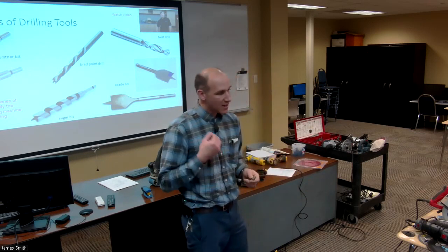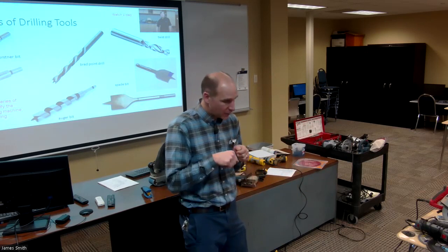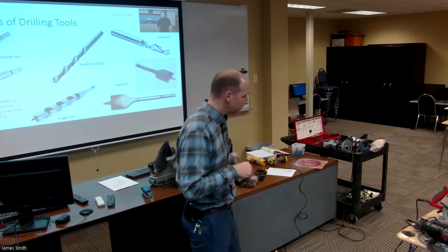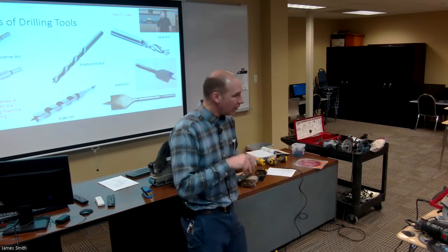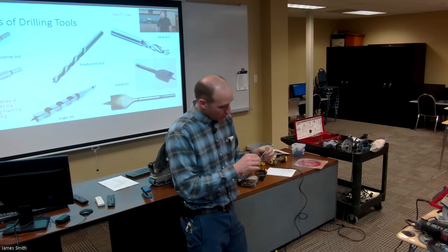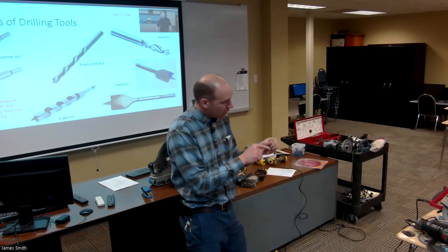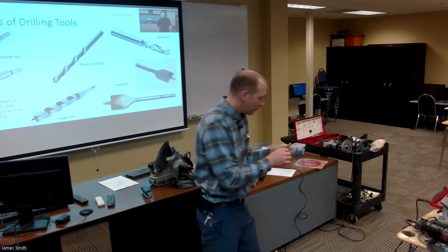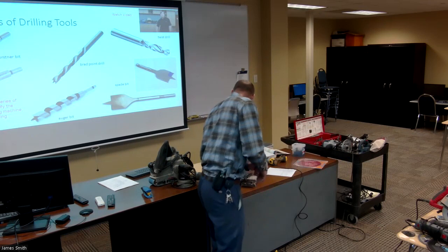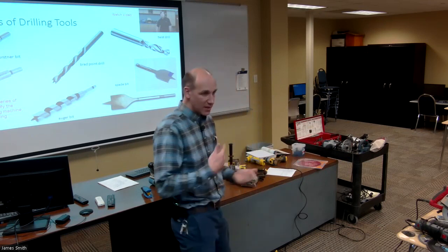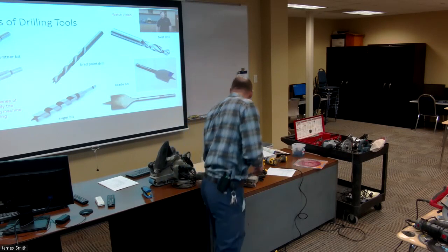The nice thing is you don't have to do it in 3 different processes, right? Using some of the old drill technology, you would drill your pilot hole, and then drill your counter bore, and then drill your countersink, and that's really not ideal. So having a bit that does 3 different operations in one is going to save you time.